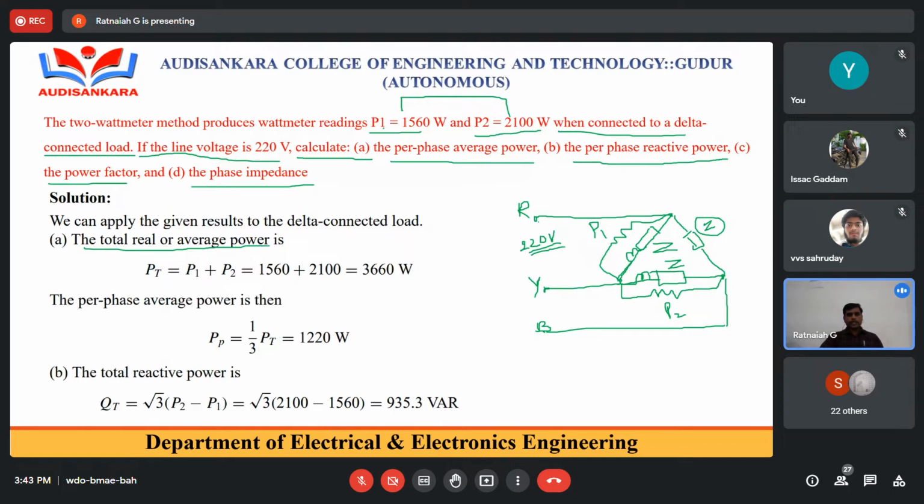Generally, we are using two wattmeters, P1 and P2. The total reading should always be the sum of both the readings, that is P1 plus P2. So 1560 plus 2100 gives 3.66 kilowatts, or 3660 watts. You can write it like this. That is the total power, the input power or total power consumed by the system.